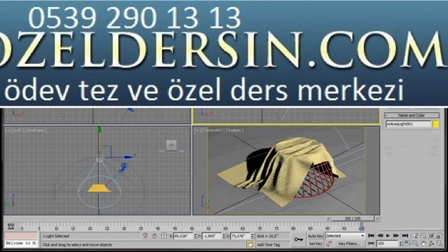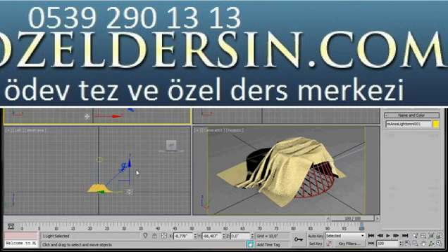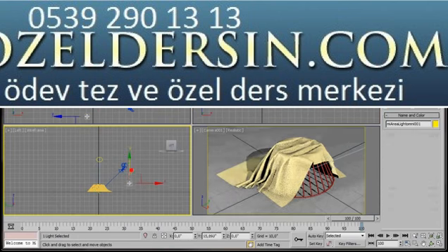Now we're going to add a couple more lights. We'll go back to the Create panel, Lights, and this time we're going to select a mental ray area omni. Go back to our top viewport and we'll drop our omni there. Right-click to come out of the Light Creator mode. And now here in the left viewport, let's drag up our omni light.